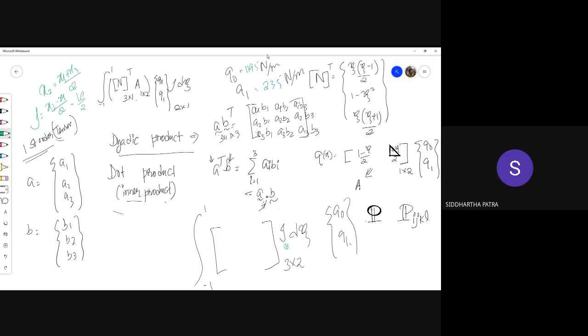So that can also come out of the integration. Because this element length could be something else also, right? 12.3 millimeter, something like that. So anything which can have an arbitrary real value, you can keep out of the integration and perform the integration with terms of xi. That way your integration becomes really easy.